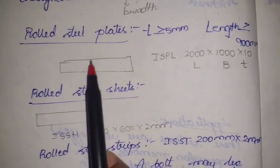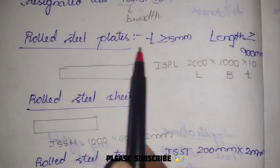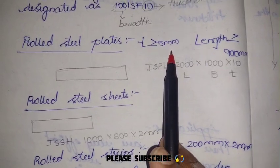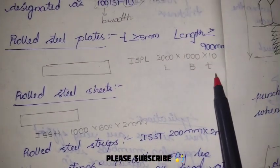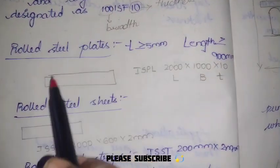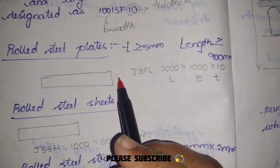Again, next we are having plates. Even here the thickness is greater than or equal to 5 mm, length should be greater than or equal to 900 mm. So this is the length, width and the thickness. Length, width, and here this is the thickness.